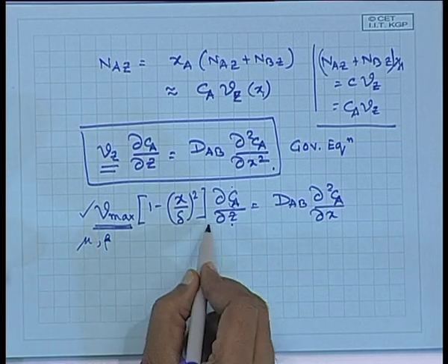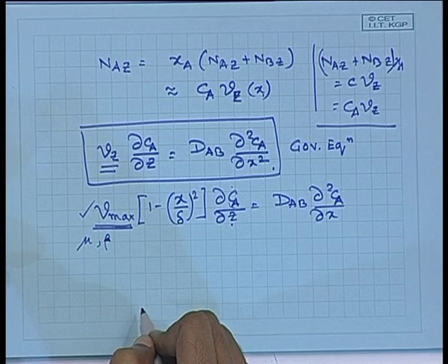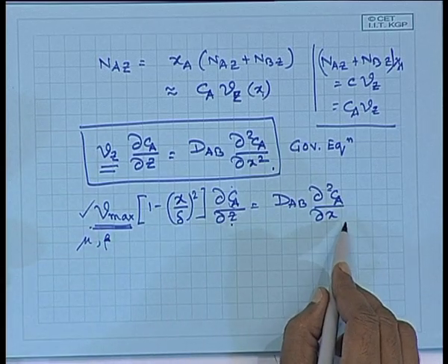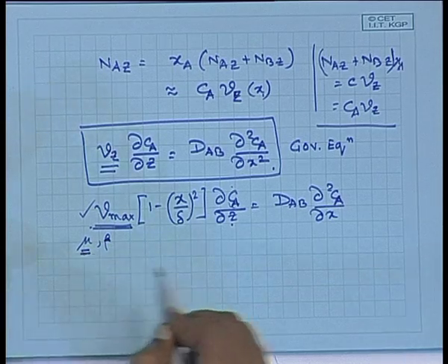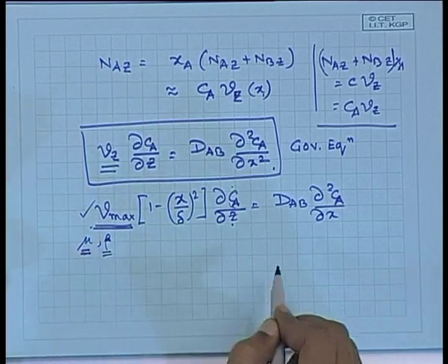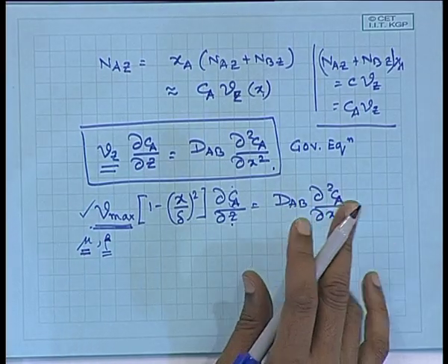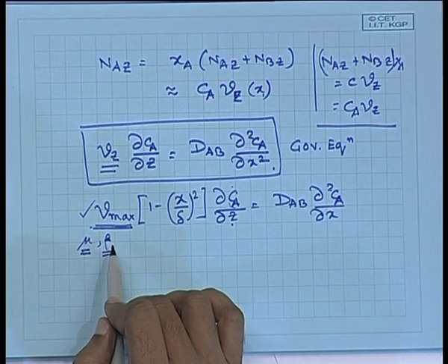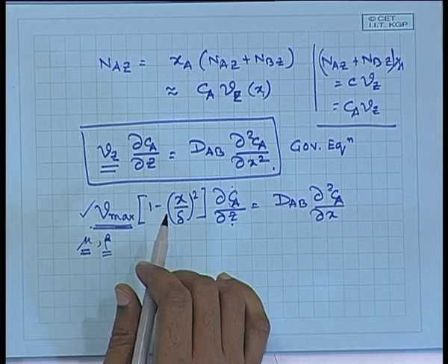When I express it in this form and integrate it, what am I assuming? Since Vmax is constant, that means the viscosity and densities of the liquid are remaining constant. And can I justify that? The density is not a strong function of other things, but viscosity is.